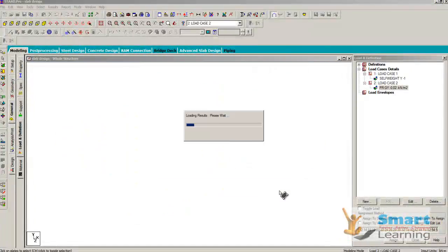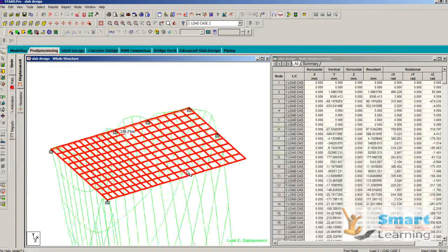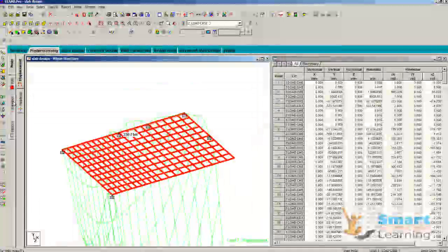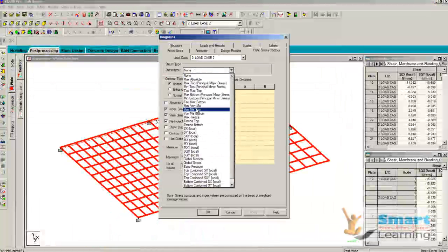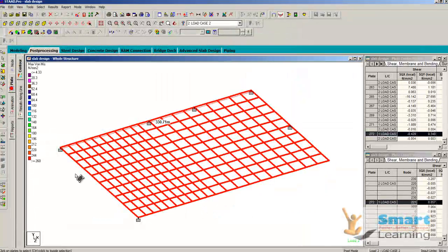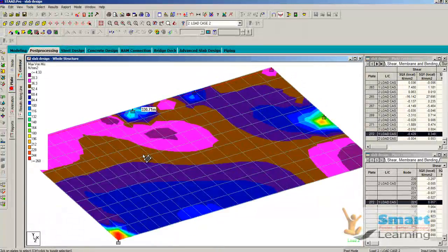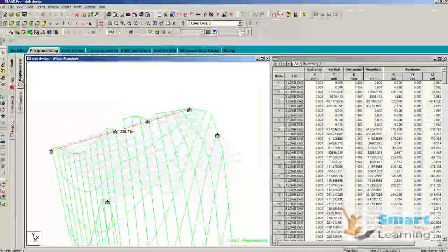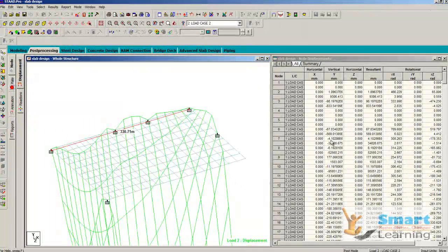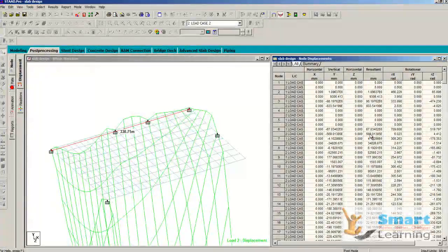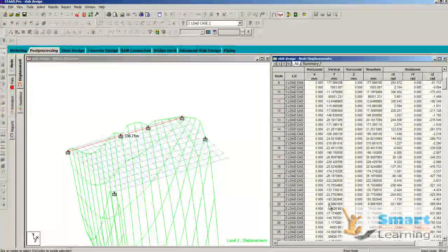Based on that, when you go for the analysis, you run this analysis and you go to the post processing against this load. Here you have the deflections, the plate Von Mises stress maximum. You can find 260 to 4.33. So 260 is the failure condition, it cannot withstand, where you are getting the maximum cases of the stress. You can see this, and also over the nodes what all maximum deflections you are getting, the deflections are very high. So 569 it cannot withstand. So based on different nodes you can see these are very high deflections, so this structure is going to fail.